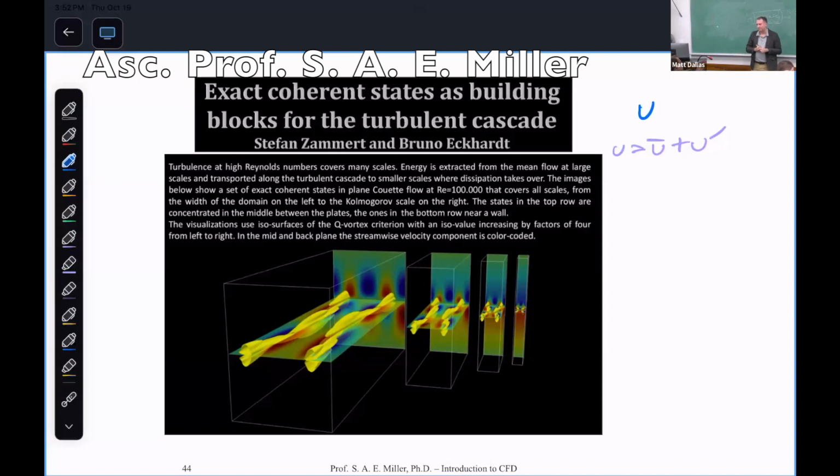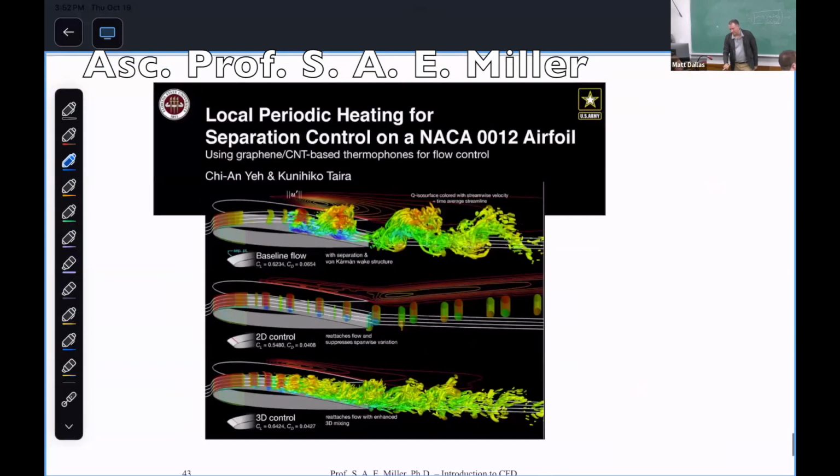Like the coarse grid is some sort of initial condition for the boundary. Yeah, so we have a coarser grid. We're filtering out the small scales and we're modeling them. So we solve more equations, but we have way fewer grid points. And then we can create flows that look like this. That's really what you're seeing. You're seeing turbulence modeling, one of two major approaches, which is grid filtering or averaging and finding statistics. So that's a great question.